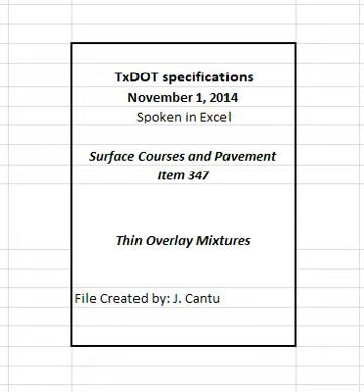4.9.2.4.3 Voids in mineral aggregates, VMA. The engineer will determine the VMA for every sublot. For sublots when the engineer does not determine asphalt binder content, the engineer will use the asphalt binder content results from QC testing performed by the contractor to determine VMA.